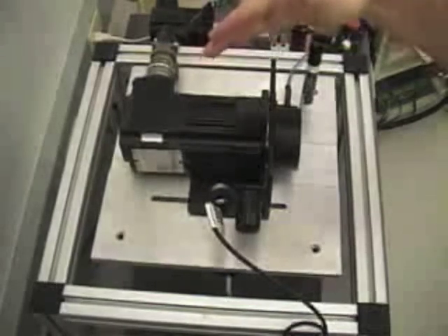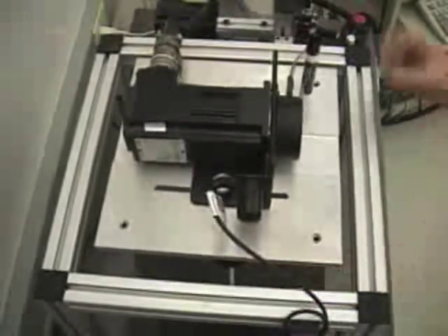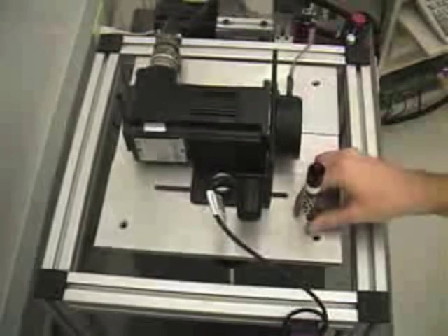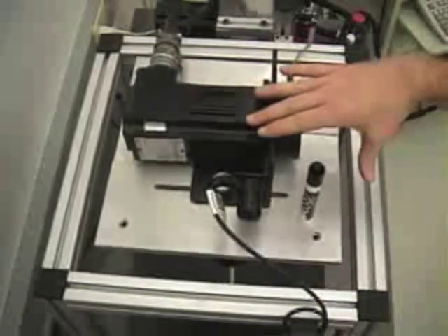Here's a top view. This is the servo motor, and here's the imbalanced mass, which is spinning. Right now it's spinning at the resonant frequency of the tuned mass spring system down here, which is vibrating. The vibrations are being basically all absorbed by the spring mass system at the bottom, so that this upper plate is almost stable.